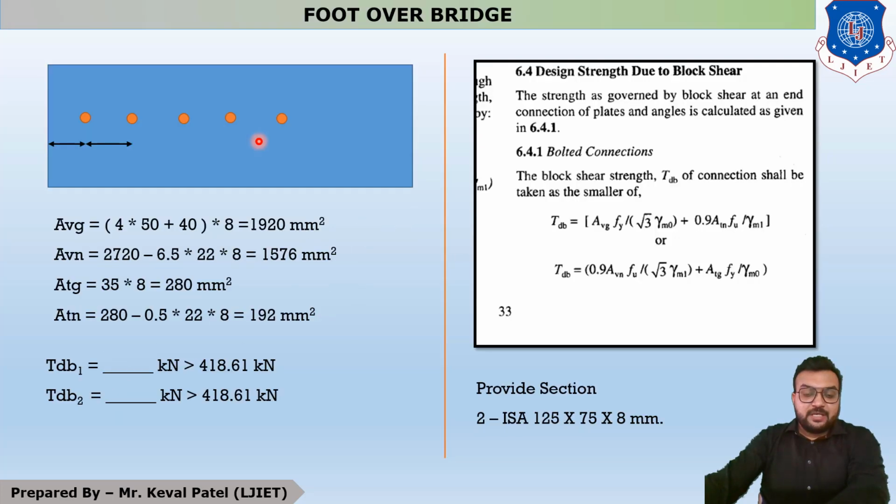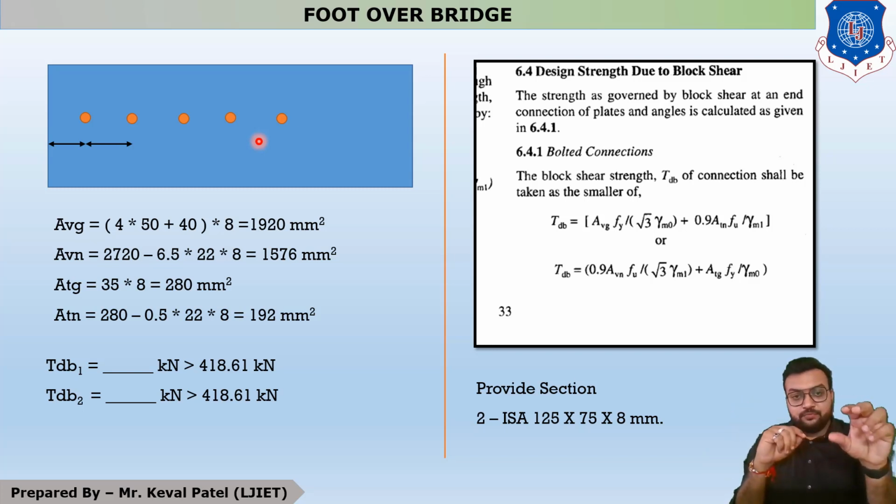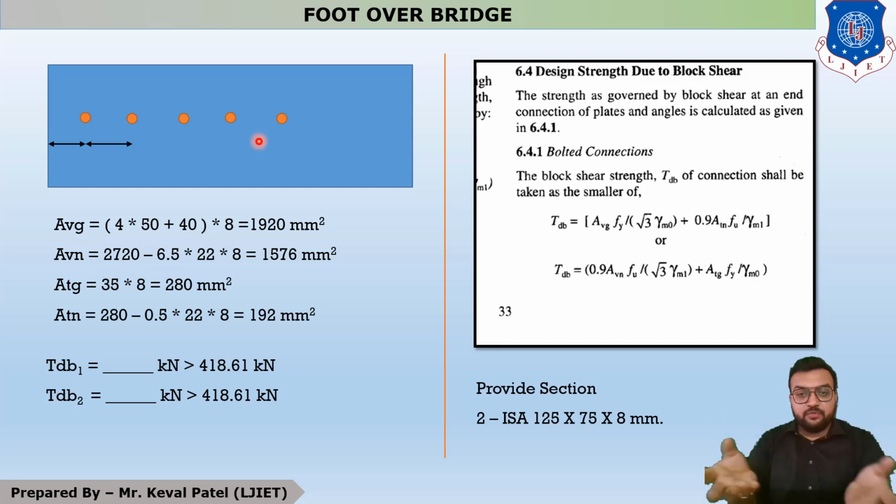And our last step is design of joint, in which we have to draw top chord force divided by bolt value, bottom chord force divided by bolt value. Okay. So all the data and all the methods will remain the same as our example number 1.